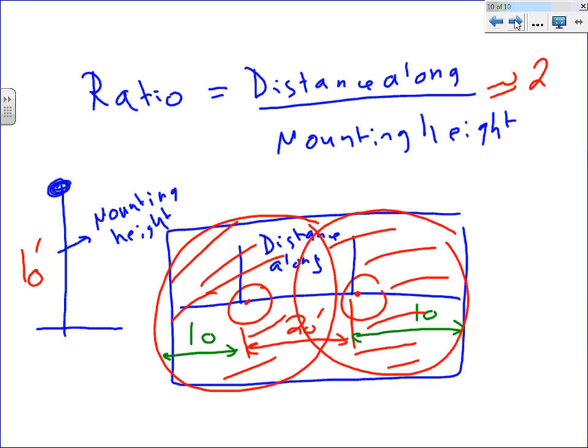One thing we didn't talk about, which we will, guys, is reflection from the wall. That's where the coefficient of utilization becomes a big deal. How much of the light that comes out actually reaches the floor or the wall versus shooting all over the directions? Or what happens to the light that hits the wall right here, bounces off the wall and hits Spencer's face? It contributes to the light, right? They call it reflected light.